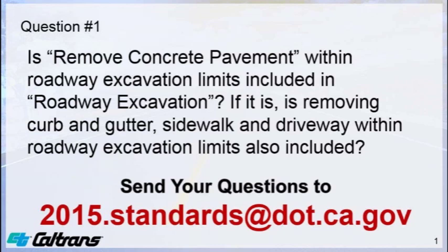And the answer is, if it's within the limits of roadway excavation, it is included in the roadway excavation payment by the cubic yard. If concrete pavement or sidewalks or other things are located outside the limits of roadway excavation, then there has to be a payment item for the removal. A separate payment item would be included.